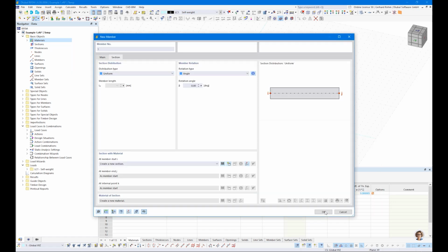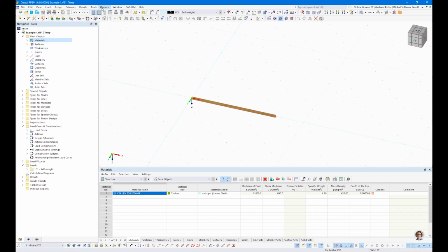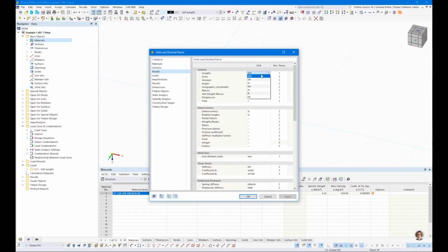Okay, so now the beam is on the cursor. We can start, for example, here in the origin and use these black grid points. I see the unit is still in millimeter. We can change this. So I go to 3 meters and the next one should be at 4,500 millimeters. So for the second span, we simply enter 4,500 millimeters and click the enter button, and that's it. So maybe let's switch the units. I have changed it in a previous file, that's why it's set to millimeters. I want to use meters here.